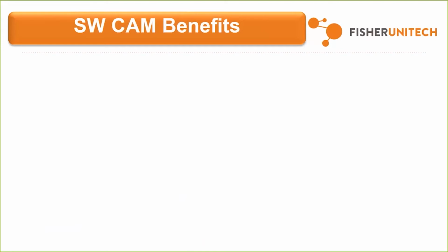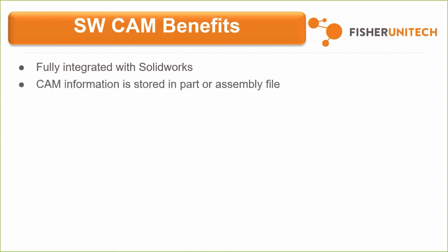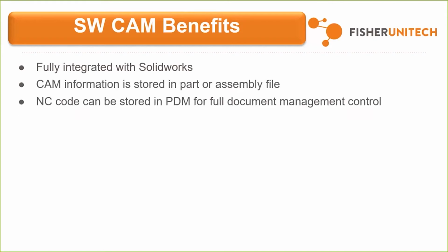So SOLIDWORKS CAM benefits. SOLIDWORKS CAM is fully integrated with SOLIDWORKS. So there's no more data translation, nothing's lost in translation because it's all right within SOLIDWORKS. The CAM information is stored right within the part or assembly file. So if I needed to save my part and send everything, including my toolpath, over to one of my coworkers, I can do that. The NC code can be stored in PDM. So if you guys have some kind of product data management system, this can be stored in PDM.